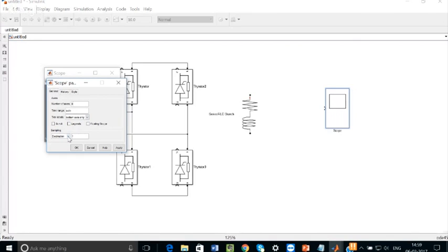And you have something called decimation. This decimation is very helpful. Say here the decimation is 1. It will take every sample. Say for every second you're taking some 10 samples, then all the samples will be taken if the decimation is 1. The sample rate also, at what rate you want to sample, I'll put a Power GUI and show you. There you have a discrete option, and if you make it discrete, you can choose how many samples you want per second, at what rate you want to sample the system. So that is all possible there.